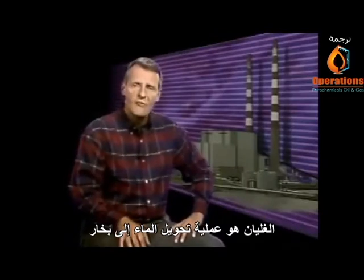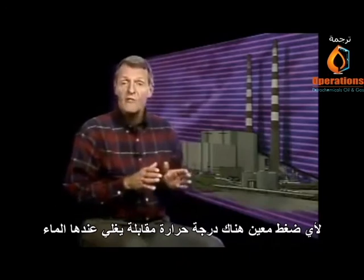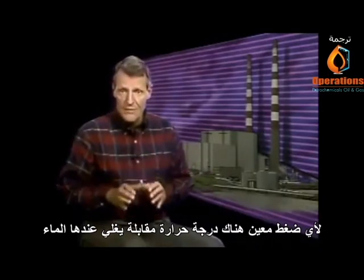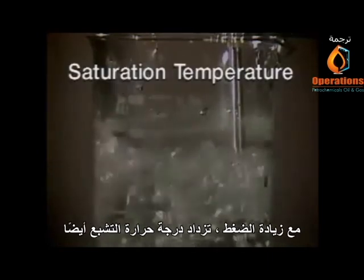Boiling is the process of converting water into steam. For any given pressure, there is a corresponding temperature at which water boils. The temperature at which water will boil at a given pressure is known as its saturation temperature. As pressure increases, saturation temperature also increases.